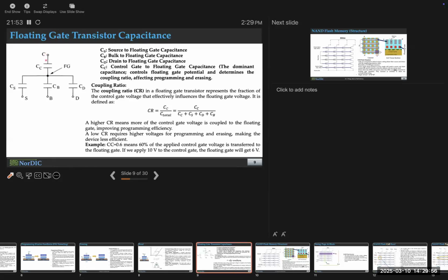So there you go. One capacitance, and these are other capacitances. Basically, this is the body capacitance of the MOSFET between the gate and the body. But there are also overlaps from the source and drain. Source overlap, drain overlap capacitance. If you remember 335, a MOSFET has capacitors everywhere. There is gate to source overlap, gate to drain overlap capacitance. So imagine the CS and CD are like that.